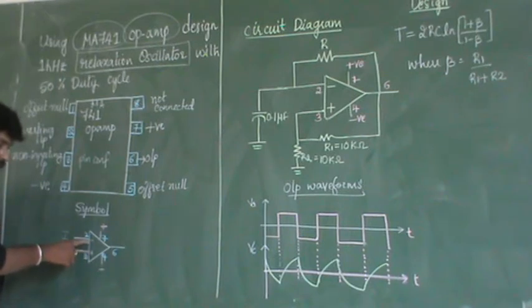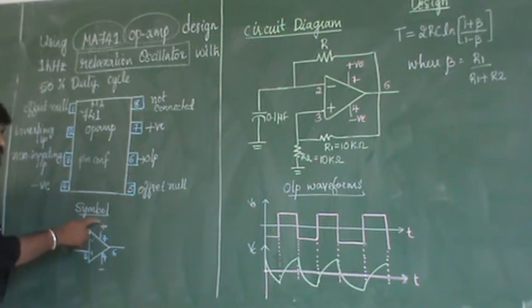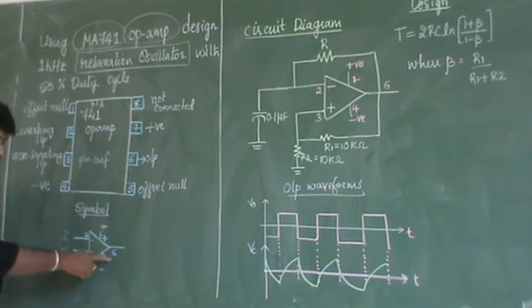Okay, these are the two terminals that are acting as input: the second and the third. The seventh you have to give for positive, and the fourth I am giving for negative, and you are extracting the output from the sixth. So the op-amp diagram is there. Totally 2 inputs, 1 output.